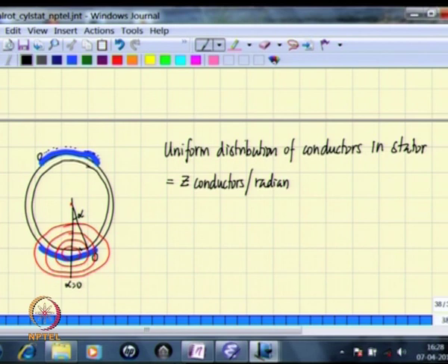Then if we take an Amperian loop that goes around at that particular angle, we can see that the MMF, or the H dot dl, would give us 2 times H into Lg, H at the air gap into Lg.